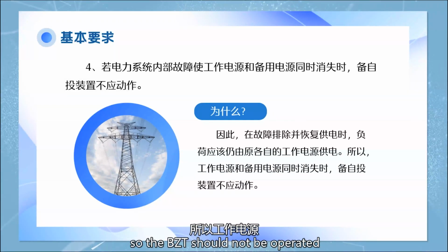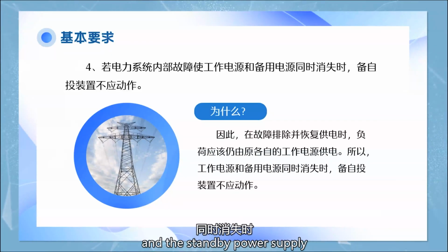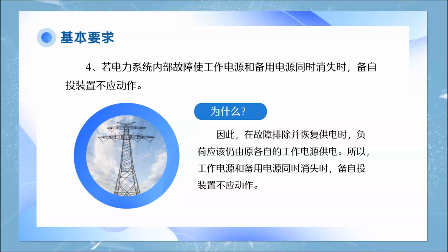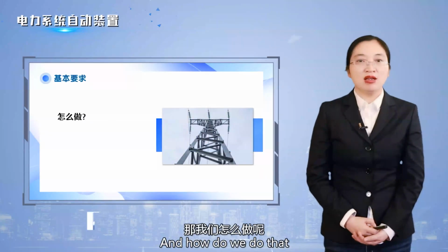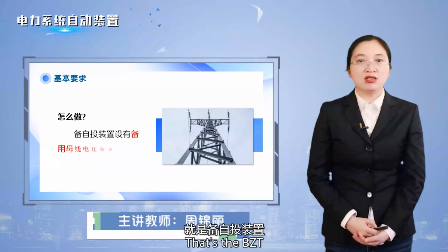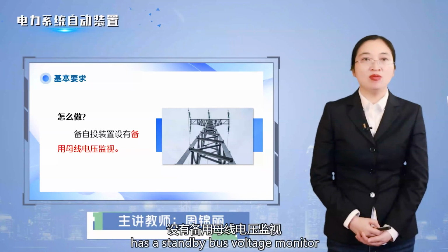So, the BZT should not be operated when the working power supply and the standby power supply disappear at the same time. And how do we do that? Thus, the BZT has a standby bus voltage monitor.